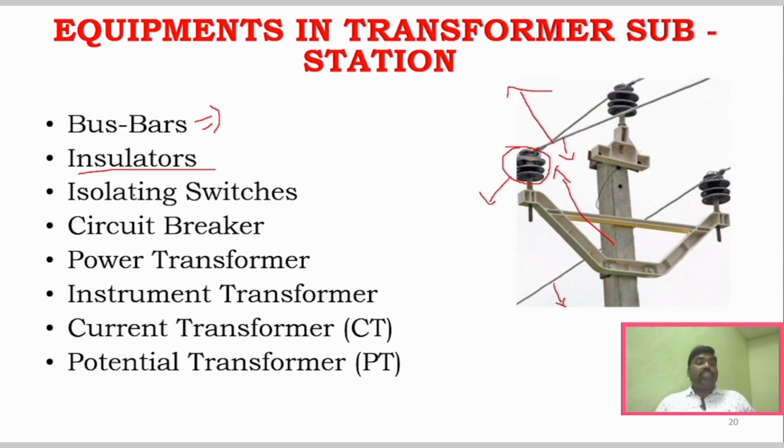And what is isolating switches? This isolating switches you would have not seen, but it is mostly used in substations where, say for example, if one particular area, not the complete system, if any one part of a transmission system has to undergo some maintenance or some repair work, then that particular part has to be isolated. So then we will use this isolating switches for maintenance and repair. It will isolate one particular part of the system.